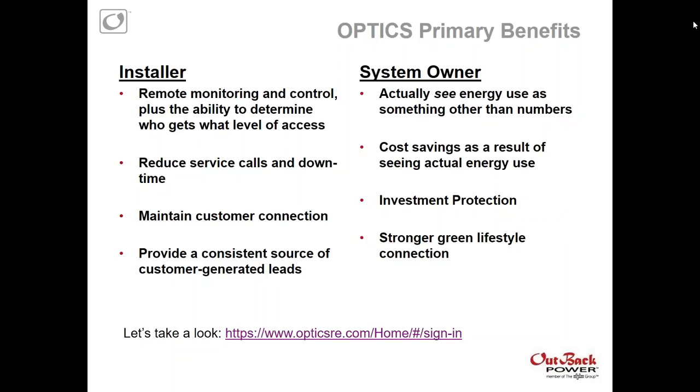But there's one more logic function in there as well. Do we have the charger on or off? Do I want to recharge my batteries from the grid at that point as well? Depending on the rate that you're paying, you may have that charger off, in which case, if you have solar, it will always use the solar to recharge the batteries. But with or without the charger, you may or may not use the grid to recharge them. Right, so you can really fine-tune it. Absolutely. Right on. That's a really cool feature.